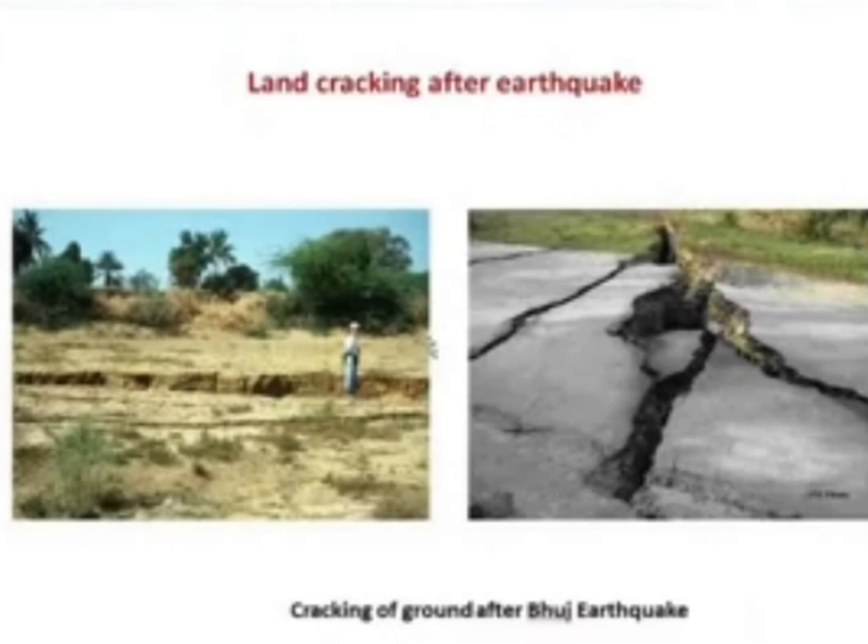We had to classify these structures depending on damage level, and some structures we recommended to demolish because you can't really go for retrofitting. It is a huge cost. Some are retrofitted, and for some minor repair was sufficient. So there were 250 structures, and I was the consultant in that project.